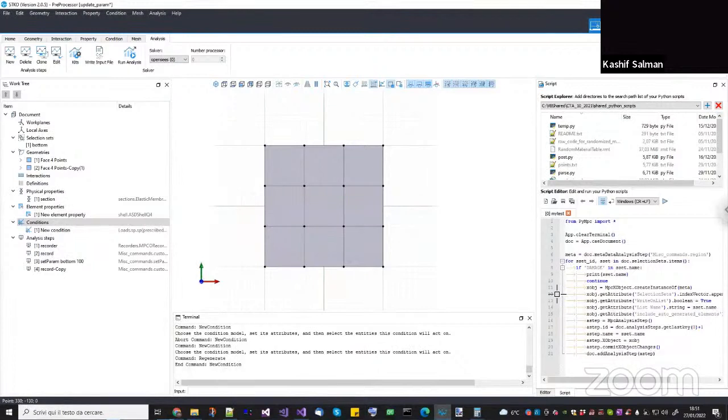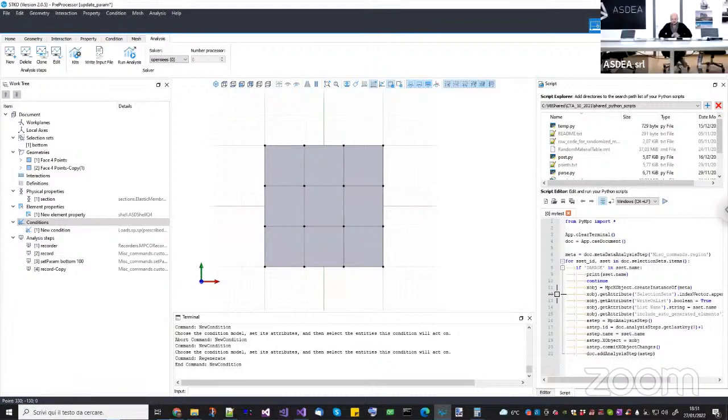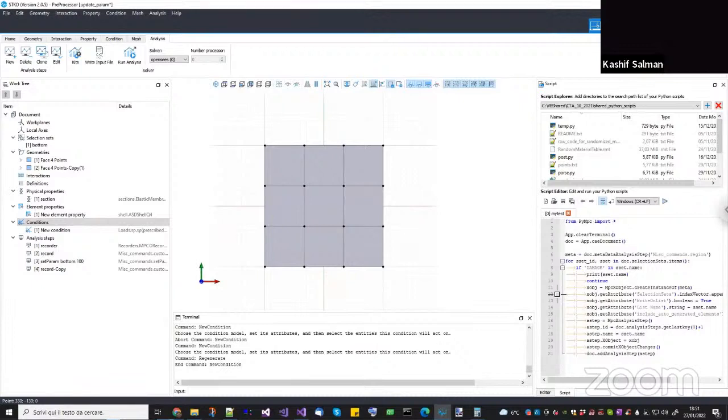The second one is the connection problem, like how to connect the non-structural component to the floor. So usually the engineers or the researchers consider it fixed, or they use the floor response spectrum method. We don't want to use the floor response spectrum method. We want a coupled analysis in which the non-structural component will be coupled to the building using anchors or screws, right? So this is the complex problem. I was looking for the interaction problem using STKO, whether we can handle it or not.